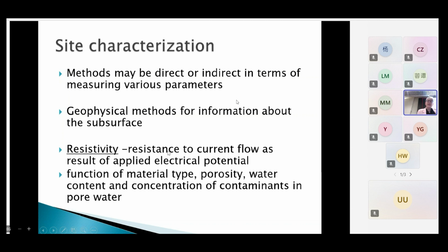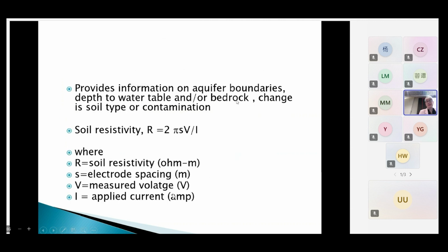So for example, for resistivity, you pass electrical current through the soil, and see what kind of characterizations and feedback you get. And you can get an idea of what kind of materials you have, what kind of porosity, the water content, and the concentration of contaminants in the pore water. So basically very indirect methods, as opposed to taking the sample, analyzing it, and knowing exactly what the...